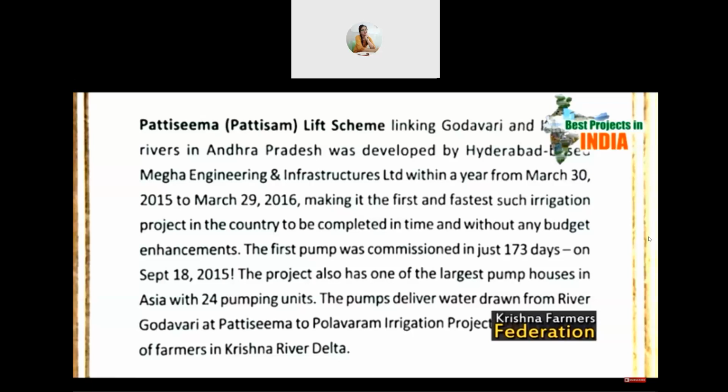Number of vertical type pumps, each 5,300 horsepower, 3.95 megawatts, to discharge 240 cumecs with 220 kilowatts substation and 12 rows of transmission main of 3.20 meter dia, 18 mm thick, used for a total length of 47.10 kilometers. First irrigation structure with diaphragm wall method of construction in black cotton soils where hard rock is met with at minus 11 meters.